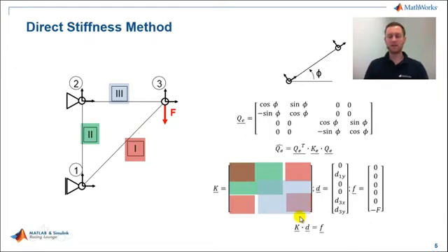This is something that you can see here. Just putting the truss stiffness matrix, depending on their degrees of freedom and the IDs of the degree of freedom, to the right position. So then we have already assembled the stiffness matrix. Then what you see here is the displacement vector D.